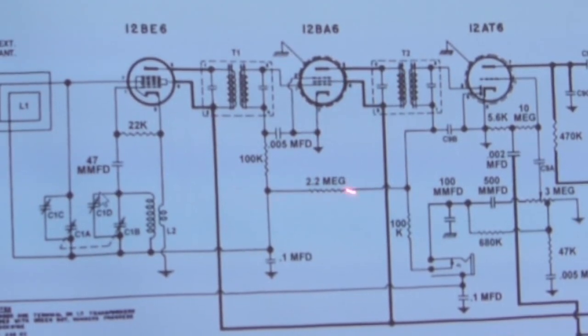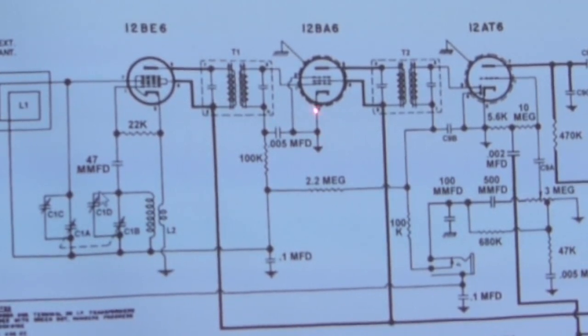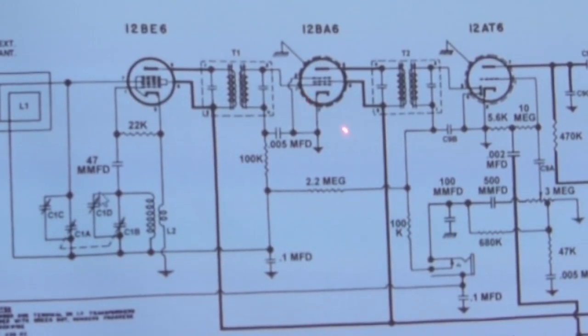It's interesting to note that all of the gain of the radio part of the circuit is right in there. The mixer itself hardly has any gain at all. You'd be lucky if it has a gain of 1, because it's devoted to the heterodyning effect, and you don't get much gain out of that. So what are you getting out of here? Well, you're getting a gain of 400 or more. And most of your radio signal amplification takes place right here in the IF stages. And that's why I guess that one is so important and why we're dealing with it. Because when things go wrong, they go tragically wrong.